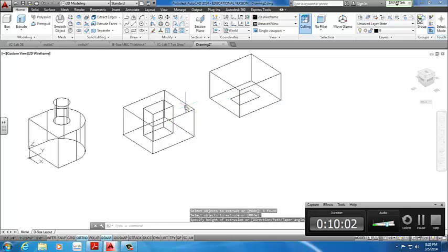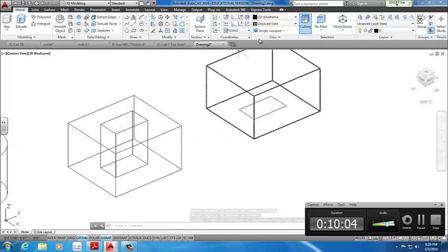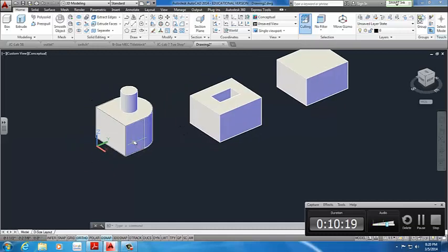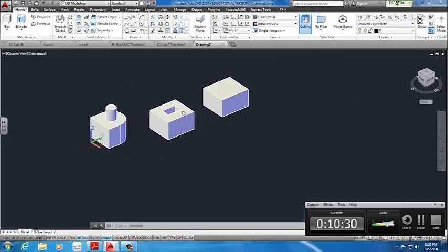Sometimes you want to remove the material from inside. So it probably would have been easier to do that whole bit right there without having to move the circle, extrude the outer thing downwards first, and then extrude the other. That is true if the item was not in separate pieces. You would have to make it one polyline to make it extrudable. So it's an additional step. So that's why I went with press pull, because it was a little faster. And it's also by preference.